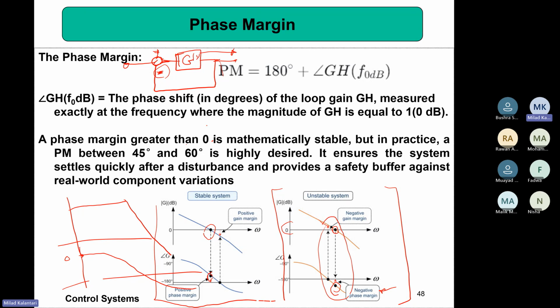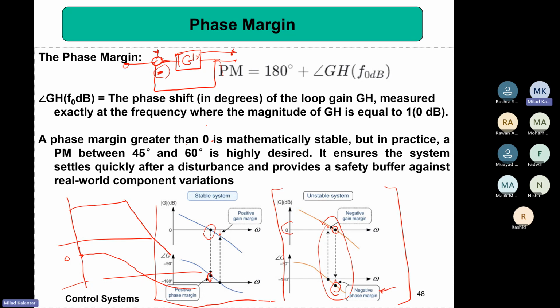And actually, this is the way that people build oscillators. So the oscillator circuit, they actually make this condition happen at a certain frequency. At a certain frequency, the feedback loop becomes a positive feedback. So it will keep increasing itself instead of confining the output. It excites itself until it reaches saturation and keeps oscillating.